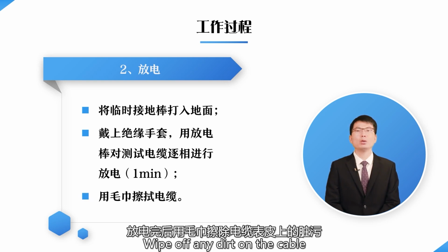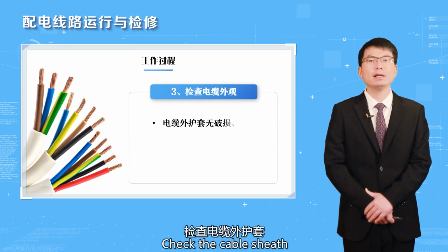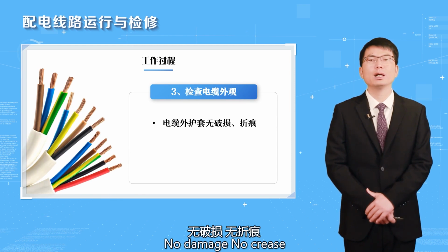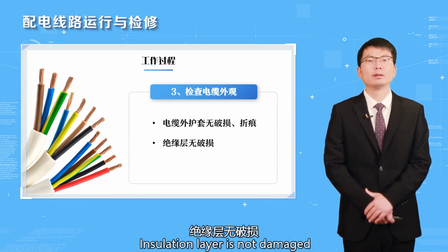Wipe off any dirt on the cable skin with a towel after discharging. Check the cable sheath: no damage, no crease. Insulation layers not damaged.